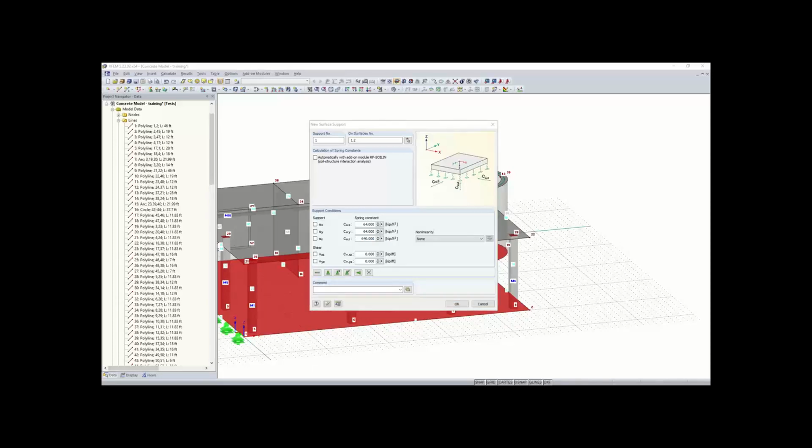And that's just going to represent the... well, Y and X are going to represent the shear capacities of the surface, and then the Z is going to represent the soil. So for our nonlinearity, we also want to take into account uplift.